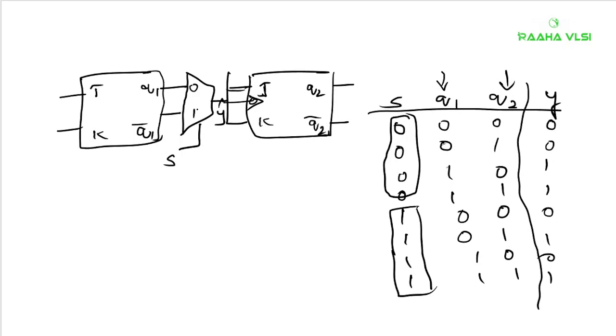Now instead of your multiplexer, we can also take the AND functionality, we know, right? So we can take two AND gates. Inside your multiplexer, you will be having this functionality only. If you want to write your multiplexer at gate level, then you will have this circuit itself. Two AND gates and one OR gate will be there. So in place of this multiplexer, you can put this.